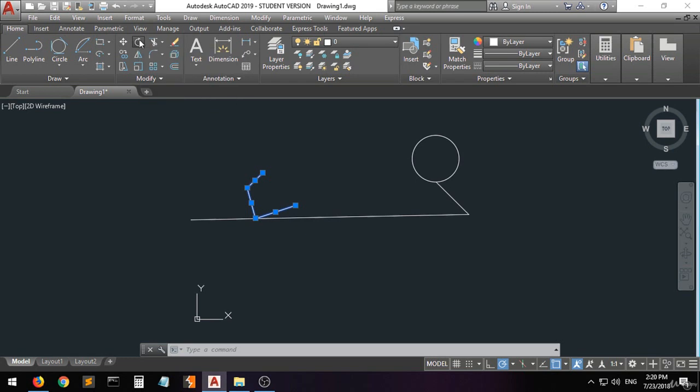We're going to use the rotate. Let's see down here in the command rotate, specify the base point. This is the base point. As you can see, I can rotate it whether in this side, this side, this side. You can rotate it in the direction you want. I want to rotate it in here. See, it is rotated. It is rotated around the point you have selected. Okay.